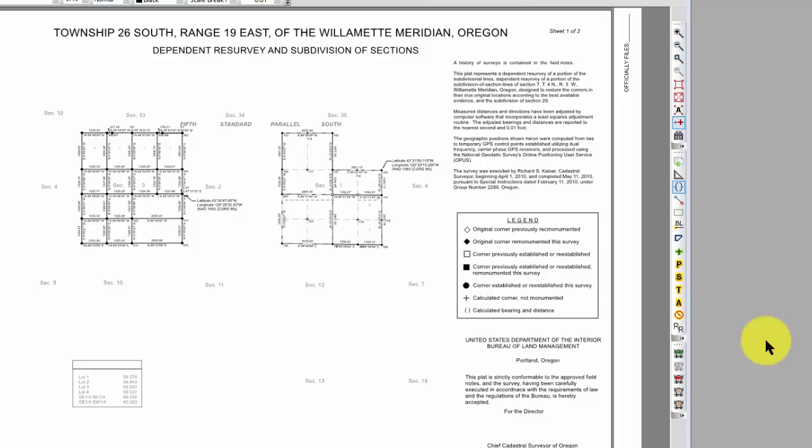And quite a difference there as you cover more distance. So that's kind of the constraints here. The other thing that the PLSS specifies is that primarily we tend to work at a project elevation, and that controls our combined factor for grid and elevation, and I'll cover that in detail here.